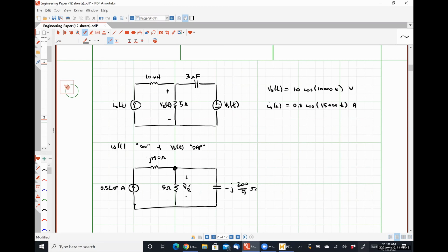There is nothing remotely wrong with that, but it's more in depth than it needs to be. What I mean by that is you're 100% correct that the current flowing into that node is known. Because those two elements are in parallel, we can just multiply it by the parallel combination and get the voltage drop over both of them. Mathematically, it's going to work out to be literally the exact same equation, but it's a little bit less thought and steps if you do it all in one go by just using Ohm's law, right?